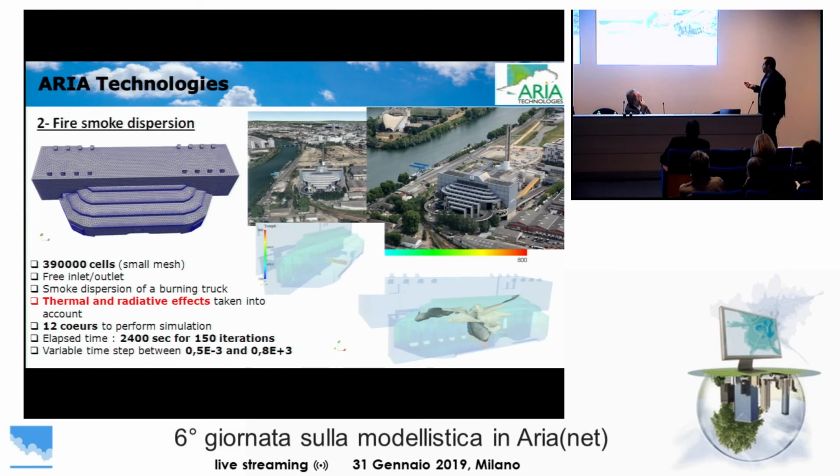Here there are some openings or closings sometimes, and they wanted to know, if a truck in the facility is burning, how the fire smoke plume will disperse in the warehouse. This is the truck with a high temperature, and we helped him to take into account radiative transfer. So here you have a very strong plume rise, of course, on the top of the truck.